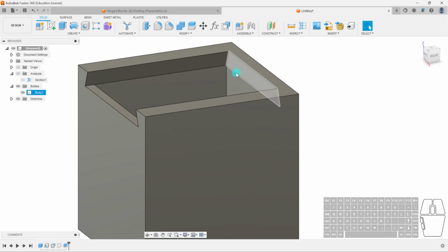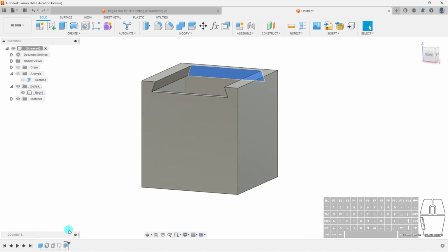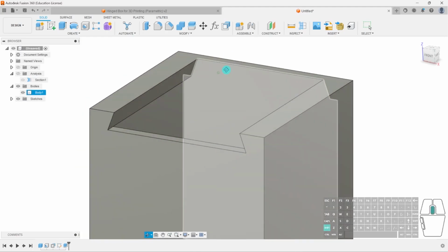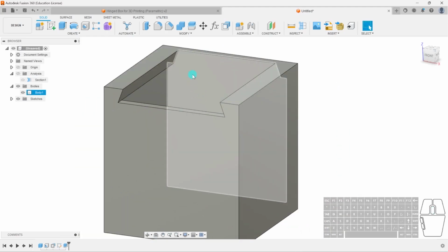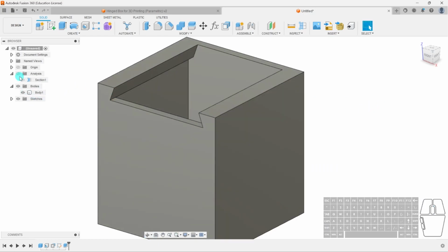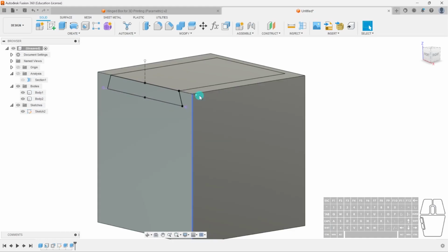In this case, we don't want it to go all the way through. We want it to just sort of go in, hit the end. For this, I don't want this to have a little thing sticking out. So what I'll do is, in my extrude, I'll just go back, and instead of extruding to a distance, I'll select the face at the back here. And when I hit OK, you can see this is all one face now. This is exactly to the edge of my wall, or the inner wall. And so the good thing with the sketch is I can then show it again. And with the same thing, I can select my sketch and extrude it out to the same one, and instead of selecting join, I hit new body, and I have my lid, as you can see, right?